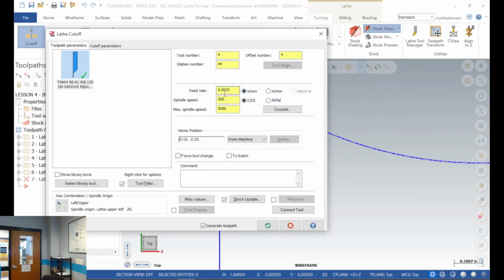On the lathe, you're going to have a lot of parts that have chamfers and radiuses on the back side. But you don't want to pick the point at the bottom of the radius because you're going to have material up there that you've got to cut away, and you want it to use that stock as recognition for the outer boundary. So you're going to use that intersection to select that point.